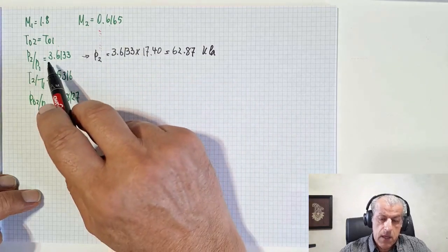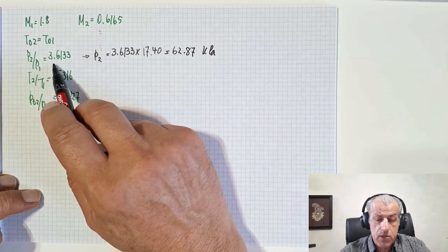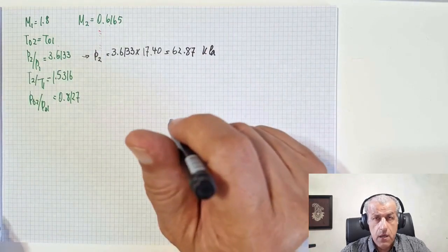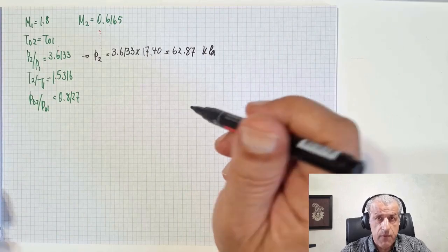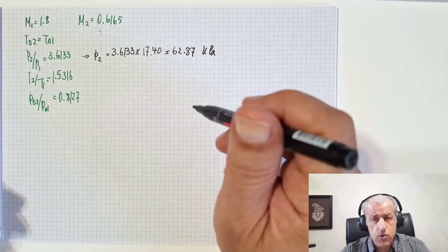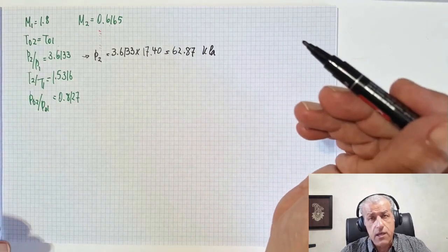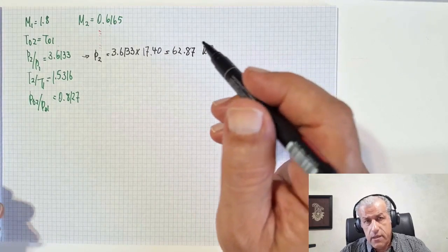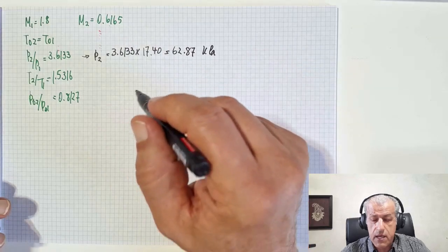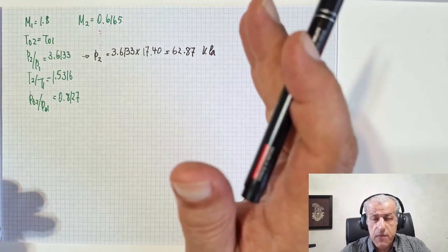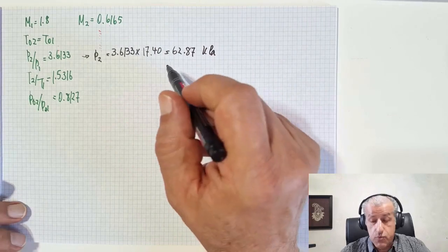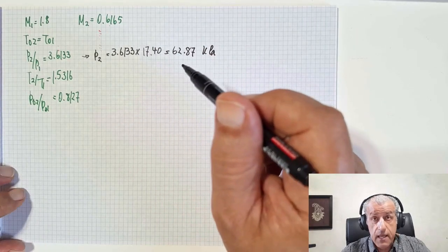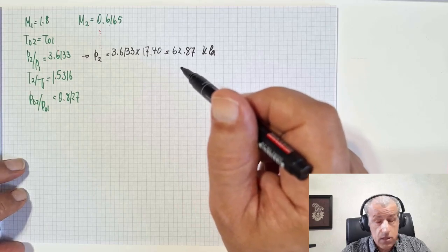You see, a compressor with a pressure ratio of 3.6 would be a large compressor and a very good performing compressor. It certainly should be a multi-stage axial compressor or a centrifugal compressor. But that's not necessarily needed here. Just a shock wave with minimum thickness would produce such a pressure ratio,